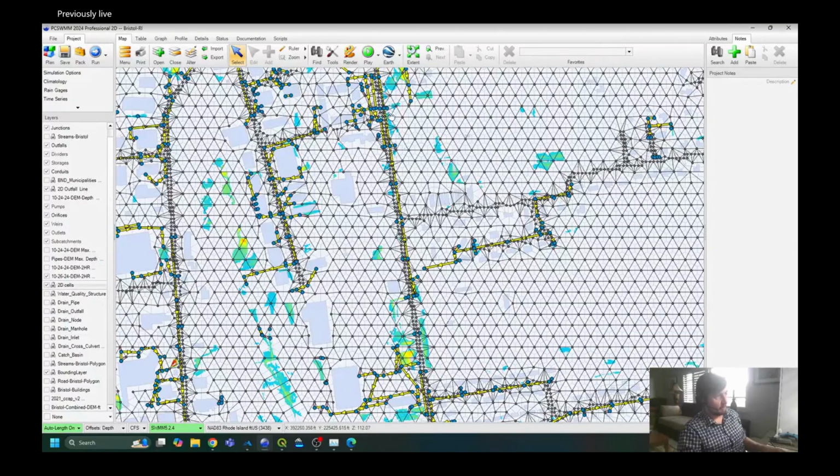So in the case of a road, for example, I know that a lot of the times roads have curbs, and I want water to have a nice ability to flow down a road because that's a lot more realistic. So I want to have a higher resolution for a road, and I definitely want to have a higher resolution for a creek or a river. And then I can get away with having a lower resolution for the surface, for the general topography of the more overland flow paths.